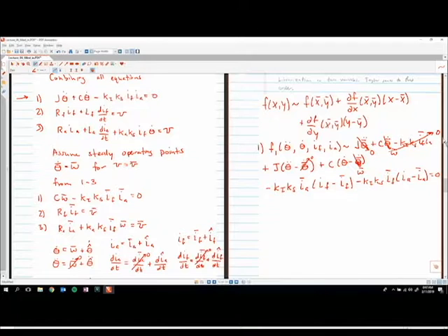So I did this in the long form just to show you how all this cancels out, but the constant terms are always going to cancel out if you do multivariate linearization and look at the steady operating parameters and basically evaluate the system at steady state and plug that back in. The constants will always cancel out. This is just showing why, but with a little practice, if you want to save time, you can always just have those go to 0.